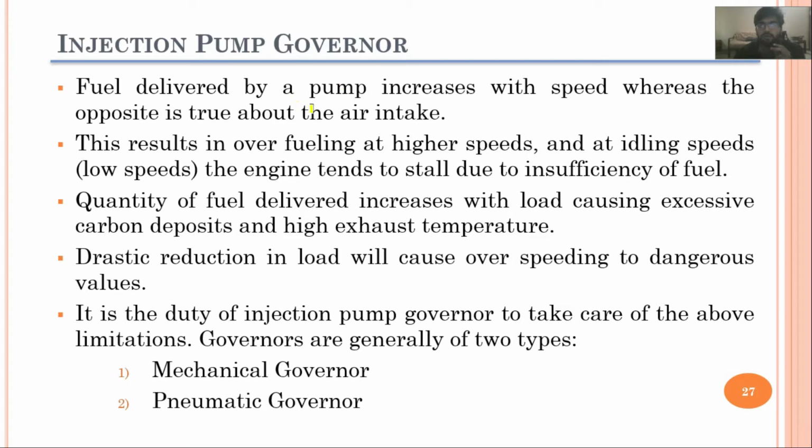Fuel delivered by a pump increases with the speed, whereas the opposite is true about the air intake. So it is mentioned here that when we press the accelerator pedal in CI engines, more fuel would be injected into the combustion chamber, and the injection speeds would also be increased.